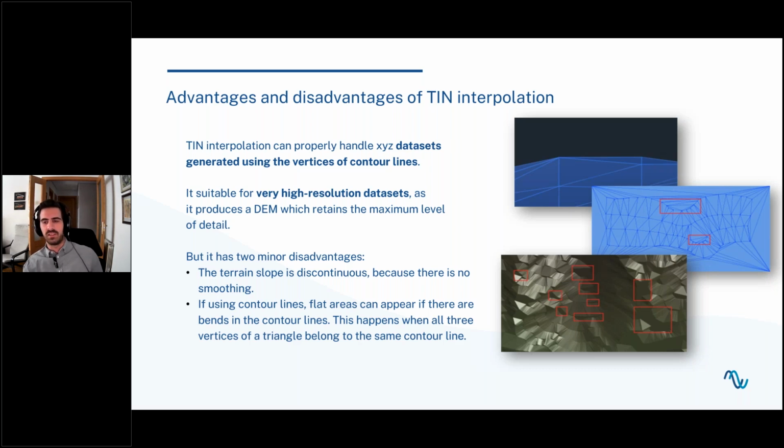And you can see that in the picture on the bottom, where it's very easy to see in the 3D, where we see terraces in that ridge line. Instead of it being a continuous ridge, it has like small steps, right? So yeah, this happens when you import something coming from contour lines. Of course, it only happens when the contour lines are very complicated.